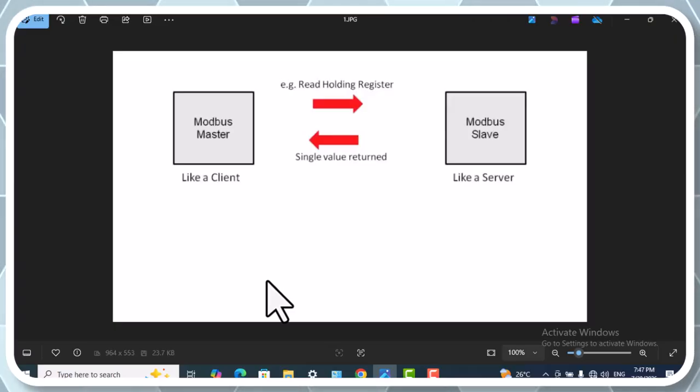OPC communication. In today's lesson we will focus on how OPC clients and servers exchange data, the difference between OPC DA, OPC HDA, OPC A and E, and the meaning of value, quality, and timestamp.